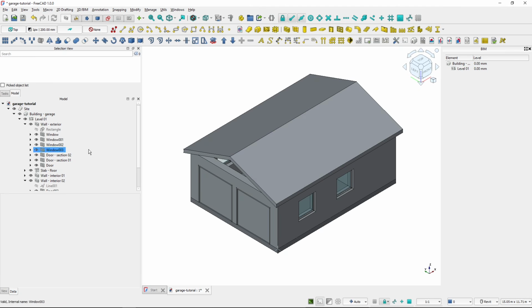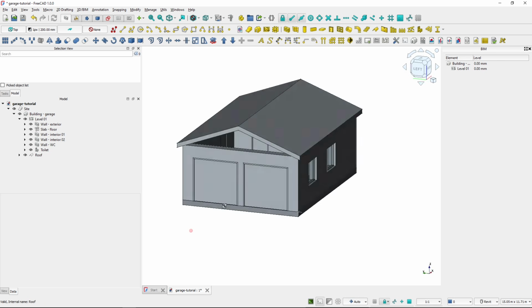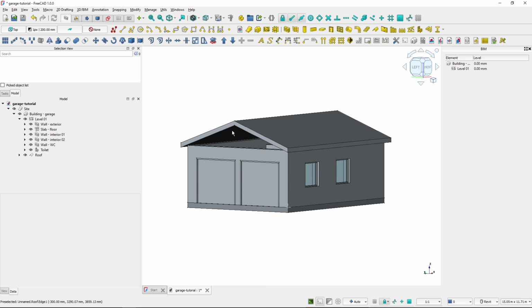So the roof is created, and now I will collapse these walls because we've got a problem of this space which is open and we want to fill it. So how do we do that? We will do that by extending the height of the wall above the roof, and then remove the roof from the wall with the arch remove tool, which is this minus.